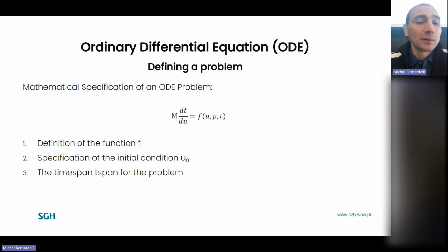And of course, the time. You will need to specify the range from what time to what time you are interested in the solution. If you get this range pretty big, then you will have to use a lot of points. And if you want all the nodes, so with the discretization of these differential equations, and if you use a lot of nodes, then the matrices and the system of linear equations that are depending on those number of points will be big, and if they are big, then we will have to spend a lot of time to get the result.